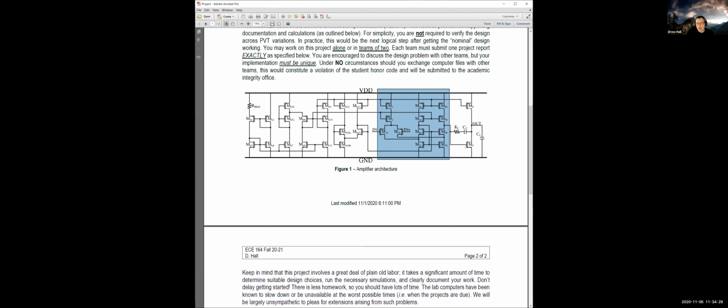But usually it's a good idea that as you go along, you think about what's going to hang off of that node. And if there is something that's critical, i.e. high impedance nodes, add some capacitance of what you expect. This allows you to hone in a little bit on the design space and not iterate quite so much.